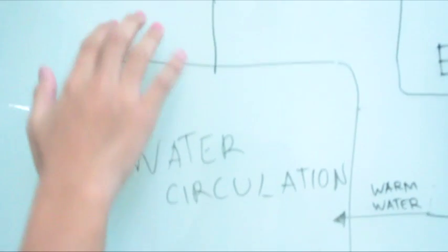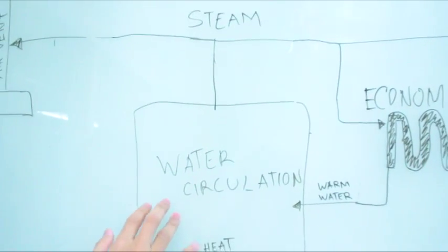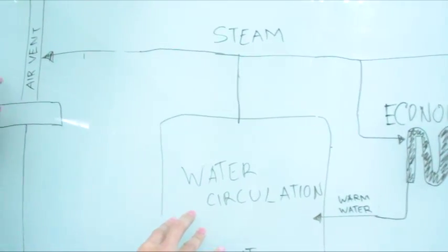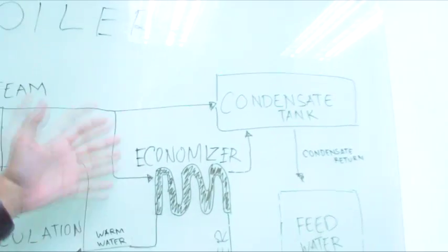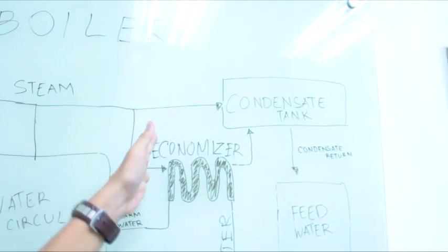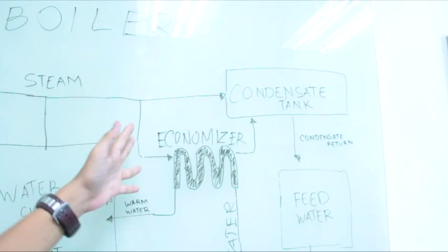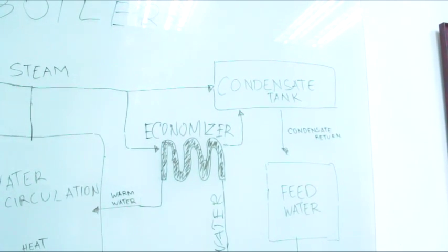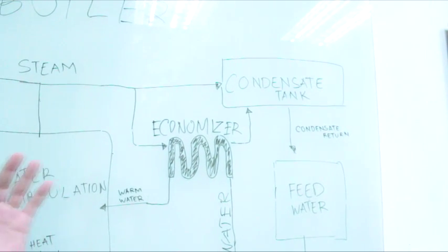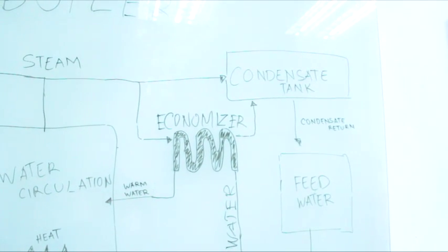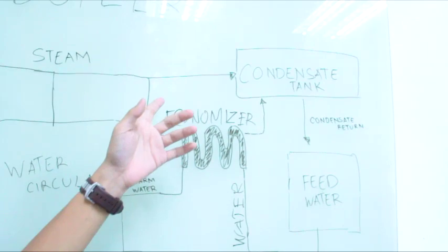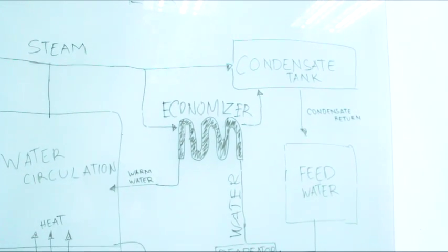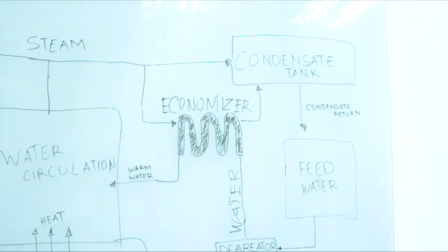After steam is released in the water circulation, air also goes in the condensate tank. If the condensate tank is not properly vented, an explosion might occur. To prevent explosion, we need to eliminate traps in the vent line, eliminate restrictions in the vent line, make the vent full size, and run the vent vertically.